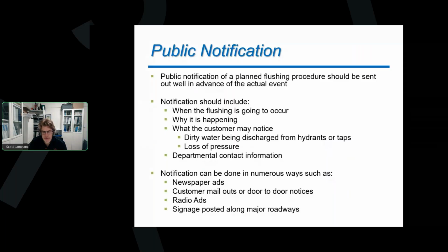Once again, before we do the actual flushing, we have to do some public notification and let everyone know what you're doing, because you are going to be stirring up a lot of debris in the main, and if someone's having a shower right on the run that you are flushing, they're going to get dirty water into their service line. So we want to let people know, try not to use water between these hours, and if you do, this is what might occur. You might see low pressure, you might see dirty water, all those things we normally put out for flushing programs, we're going to put out for a UDF also.